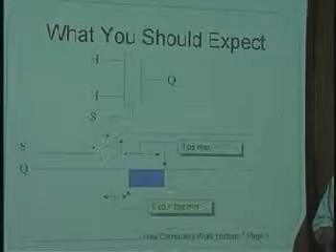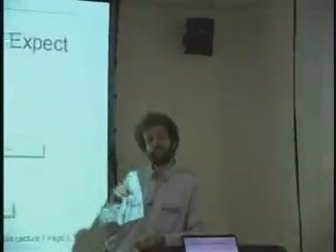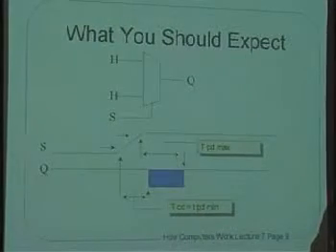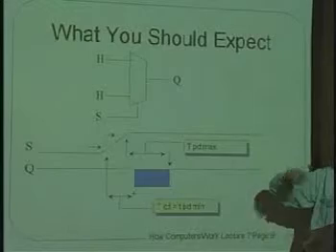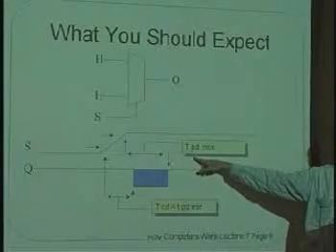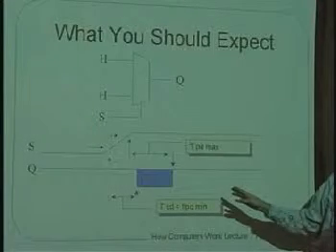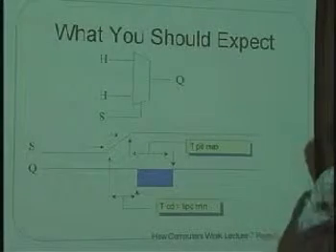But it's actually okay. Inside of your computer, at any given time, a lot of the wires are in these intermediate states. And what's great about it is that the succeeding circuits are not looking at the wire when it's doing that. If you remember our finite state machine timing diagram, that D flip-flop, the D register, did not sample its input until after all of this blue time was done. It waited until the TPD max had finished of one circuit, and then the next one, and then the T setup was done, and then we triggered it. Okay, so it's okay for these glitches and stuff to go on, as long as we're not watching the signal when it's going on.